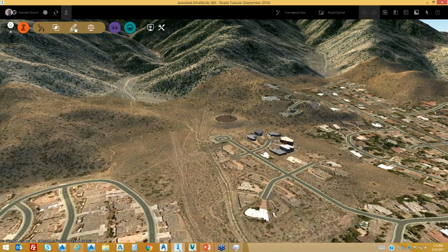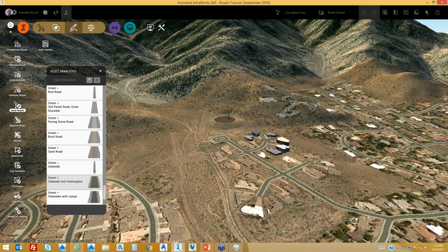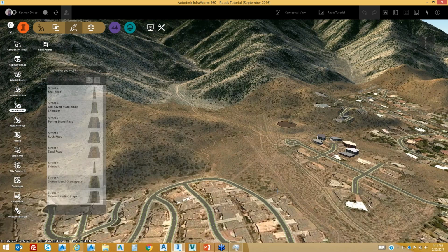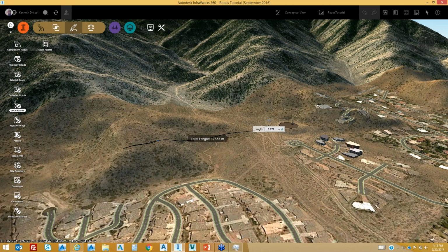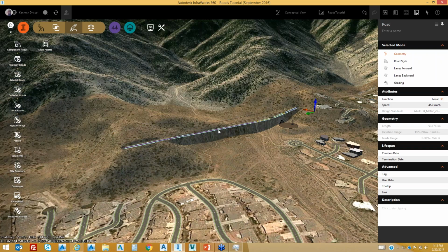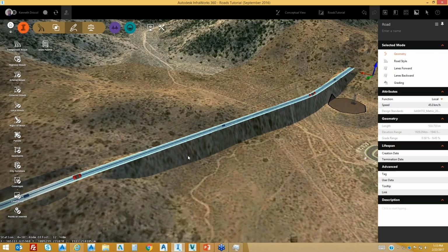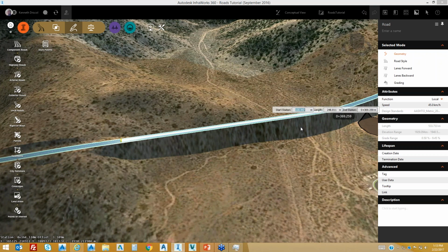I'm going to lay out just a regular road as I did previously. So I'm just going to pick here, here, come down here, and double pick there. So again, the idea of my road or bridge, I can right click and just add a bridge. So I'm going to go from here all the way to here.